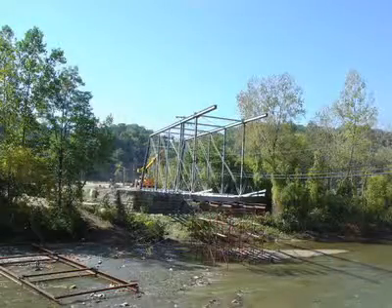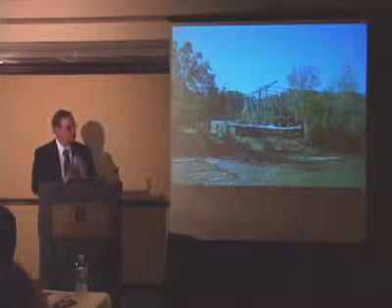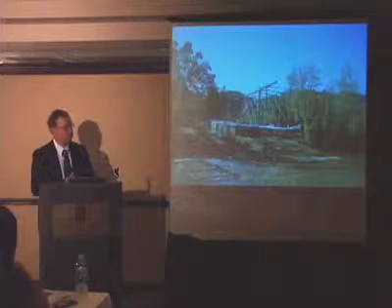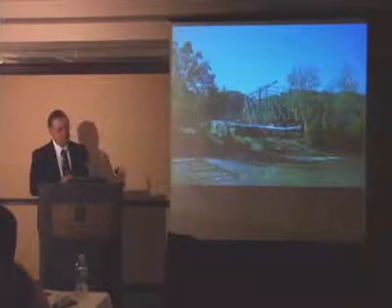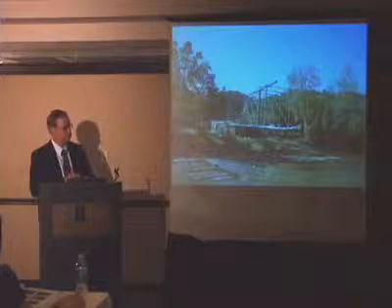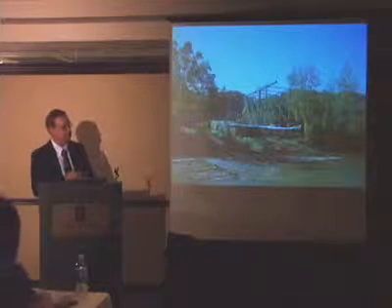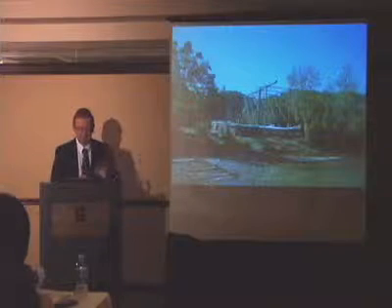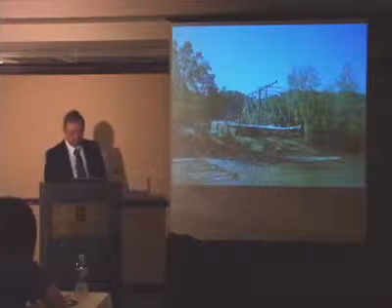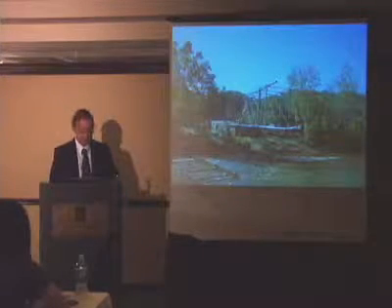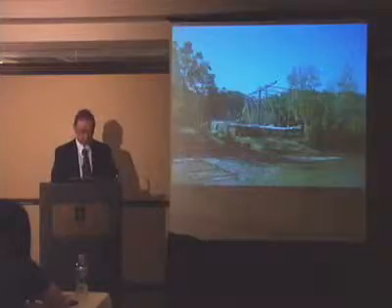This bridge was disassembled using scaffolding set in the creek. The creek bed was solid rock. The unit was taken apart, set off to the side with cranes, disassembled into smaller pieces, transported back to the shop, rehabbed, metallized, brought back to the site, reassembled. Each unit was set in the creek using a spreader frame to pick up the units.